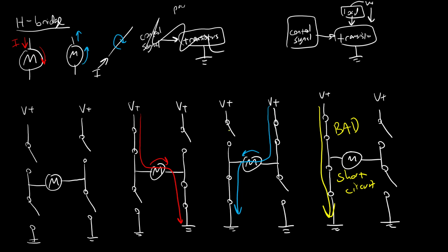You could do this with transistors, either the BJTs or NPN BJTs or N-channel MOSFETs we saw in the previous couple videos. You could replace each of these 4 switches with a transistor that you can then control electronically. So if I just draw that here in a different color, I'm going to make my diagram a little messy.